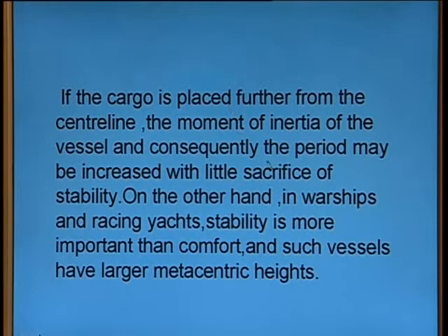And in case of warships or racing yachts, stability is most important, so in that case also the metacentric height is kept more. So if we increase the metacentric height, we reduce the comfort level of the human beings moving in those ships. We have to keep this in mind, and we have to compromise between stability and comfort depending on our design criteria.